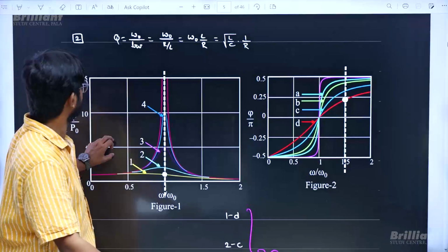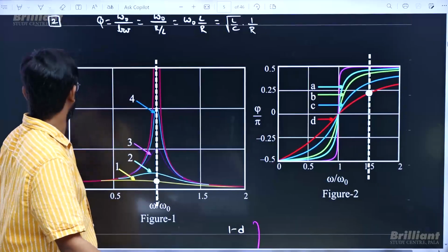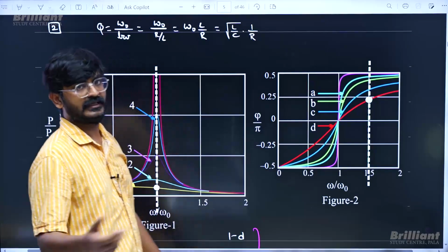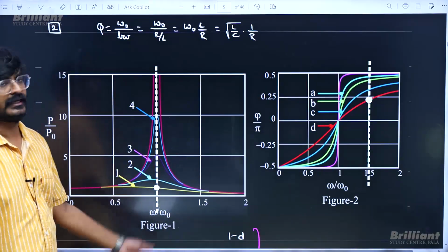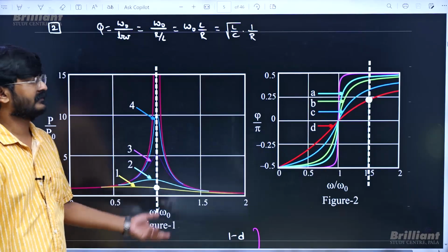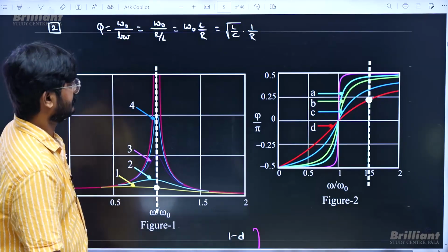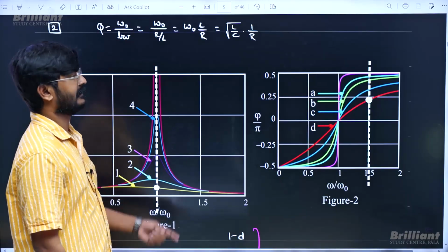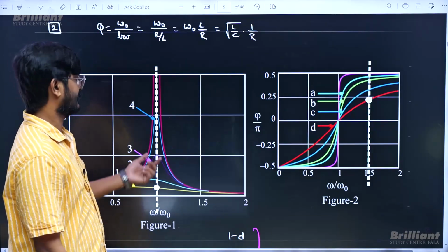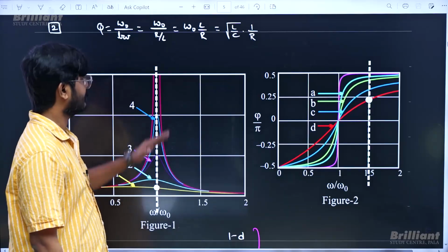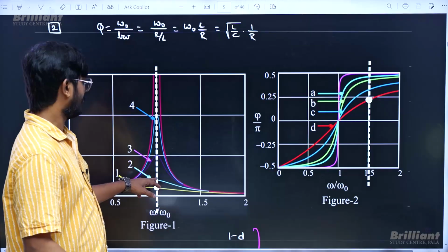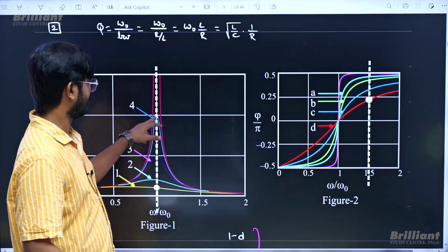Now if you notice, there are lot many things which can vary, but let me go with a simple case where L and C are fixed and I will be varying R. If I vary R by keeping L and C fixed, still I can vary the quality factor. Now if I keep varying R, for first situation when R is R1, let me say the curve is like this. For second case it is like this, third case it is like this, and so on. You can see power is maximum for this one, next for this one, next for this one.